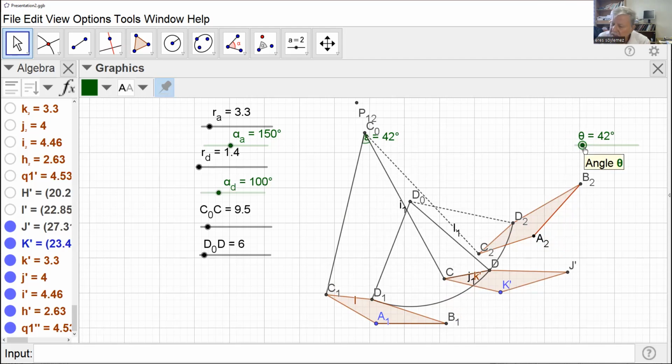Now, depending on the application, depending on the practical problem, one solution will be better than the other. You have to check the transmission angle. You have to make sure that your mechanism moves in between the positions, correct? You must check the transmission angle, for example, because if you are going to transmit large forces, it will be a problem.